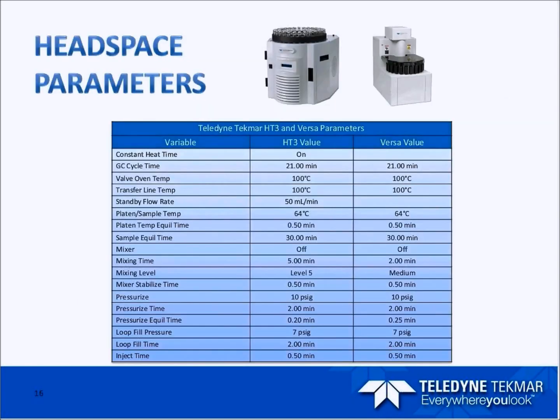Okay, the next is kind of the general. These are our methods for our headspace analyzers, the HC3 and the Versa. Since it's a loop-only method on the headspace via BOL 6019, it's a headspace or loop-only method. Sorry, you can run it on either instrument. They both have a loop on them, so either one can do it.